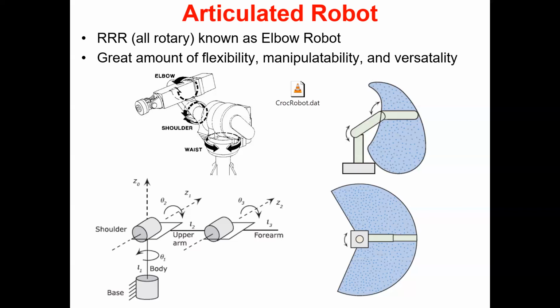If you look at a Cartesian robot, for example, the robot is big and the workspace is inside the robot. The Cartesian one operates within itself, right? The accessible volume is well inside the robot. The robot is bigger than the workspace. But when it comes to articulated, the robot is very small compared with the volume.